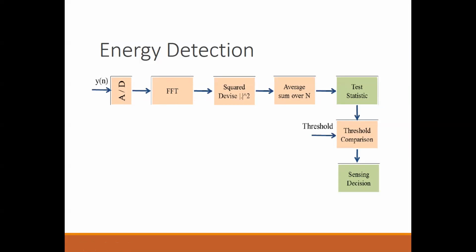But if you want a higher resolution, you have to increase the sampling frequency fs. Increasing fs means your A to D converter is working faster. So the overall resolution determines how fast the clock works here. Is my point clear? So if you take an FFT and want a finer estimate of the spectrum, you have to go for higher and higher sampling frequency. I will come to that point later again. The other blocks are quite trivial, and I don't need to explain much about them, but I wanted to tell you what exactly the problem is in this kind of method.